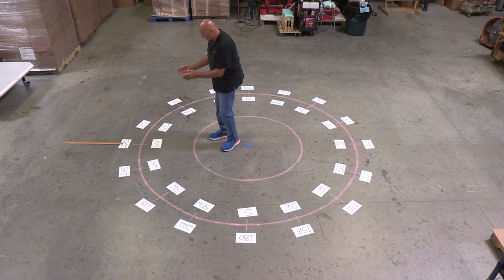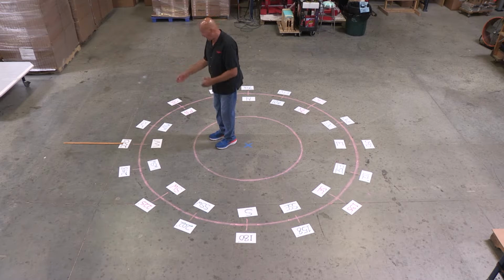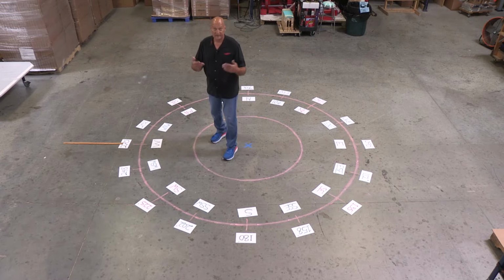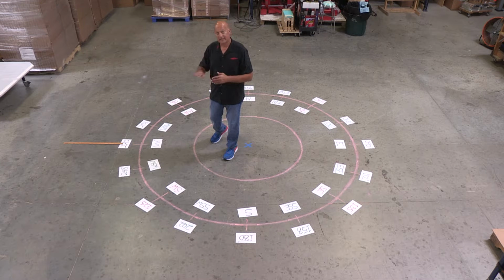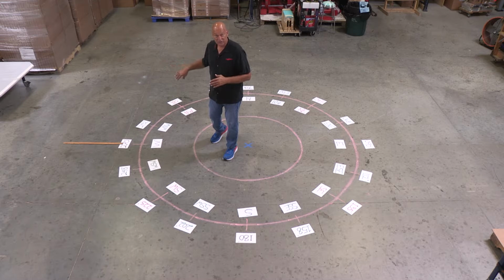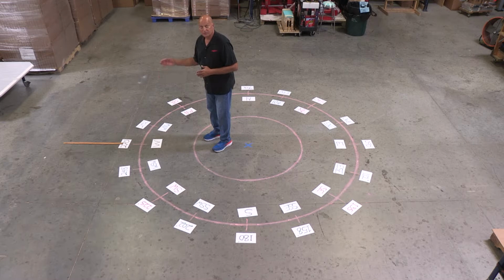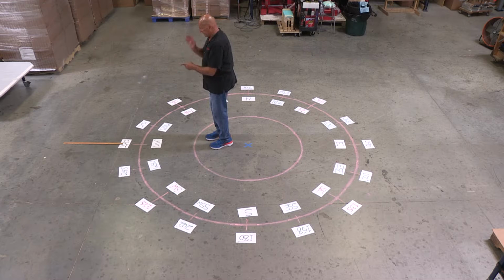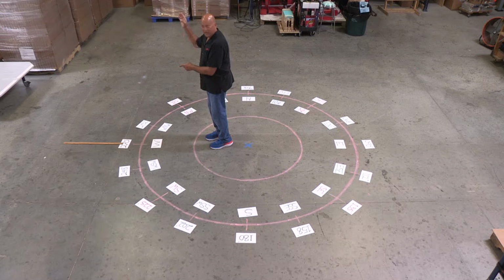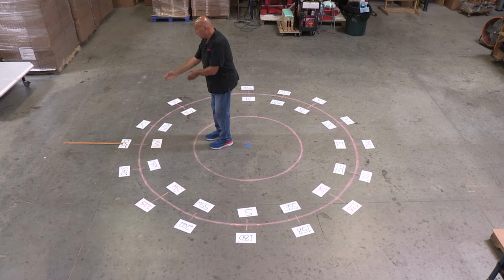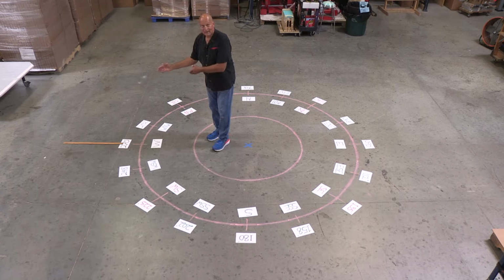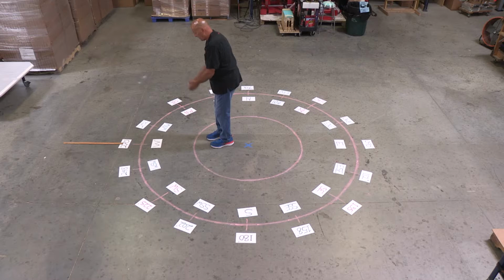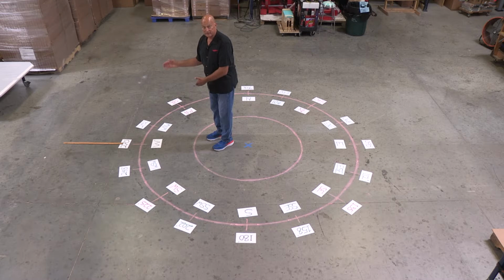So then the student can look at that as a representation of the runway and say, okay, remember the rules about how we number the runways magnetically and lop off that last digit. So in this case, I want to see 2-7 right here at the piano keys. I want to see 2-7 there. I want to see 2-7 on my HSI. I want to see 2-7 here on my wet compass. And so I use that meter stick as that representation, so they understand here again that directional importance of this compass rose.